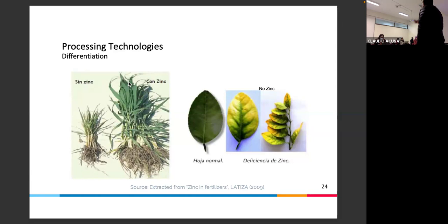Perhaps you already know, but the basic KPI always would be kilograms of water or liter of water per ton of material that you process. It's called the water footprint. CO2, kilowatt hour, how many kilograms of reagents do you need, labor. These numbers are important to determine at the end the cost of the product. You need to do all this stuff. So in this example, the whole project is already done. You will see even the economical evaluation. So the assignment will be same thing, but with different product.